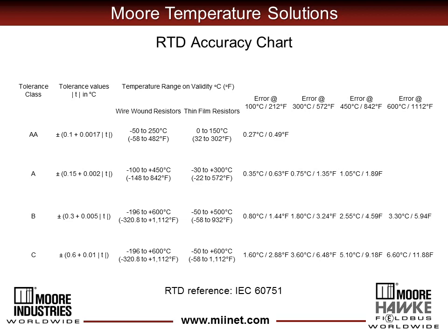And then going from a premium grade thermocouple to an RTD, you cut your error in half again. So again, we're back to sensor selection being very important to measurement accuracy.